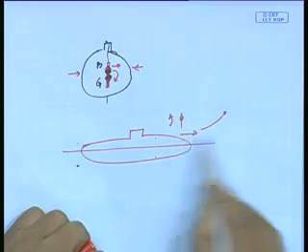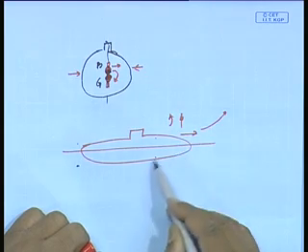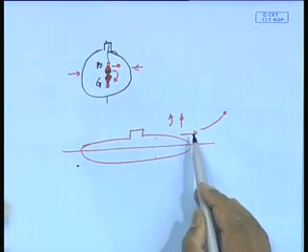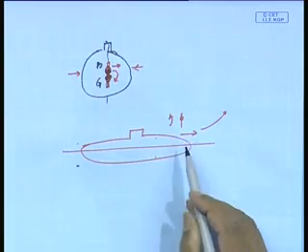But what I am saying is, in a straight line motion also, unlike in a ship, because there is no buoyancy equal to weight, hydrodynamic force becomes much more critical. In a ship, in this plane, you push it down, buoyancy will push it up. Buoyancy force is so large, right? You push it down, it gets pushed up. But in a submarine, you push it down, it comes down. So, what will actually cause it to go up? Only hydrodynamic force. So the role of hydrodynamics becomes even more critical in the vertical plane for submerged bodies. Slight forces can cause it to drift. And I was remembering that, with slight forces, there is no propeller, but the body keeps drifting.